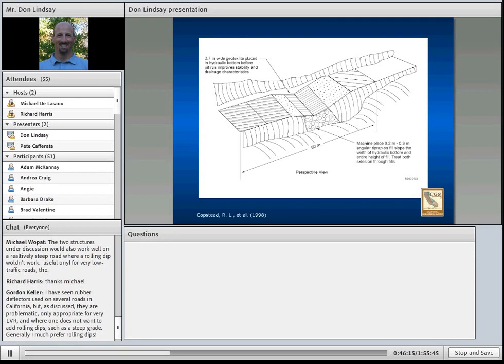Although it is seldom done today for dips, the size of rock required can be calculated and is a function of the slope of the fill face, the density and angularity of the riprap, and the anticipated flows. For a typical installation, one with the fill slope inclined to 2 to 1, and with flows less than about 6 CFS, the common mean diameter rock would be about 10 inches.